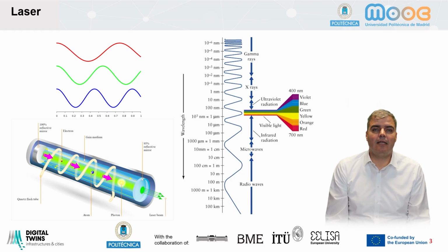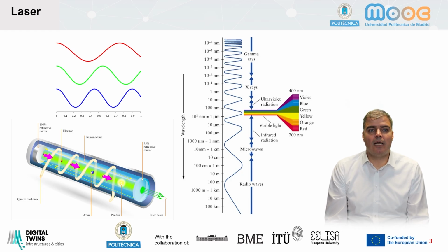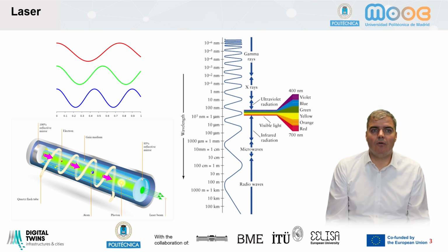The near infrared range that laser scanners use is around 1 micrometer, 1.5 micrometers, 1,500 nanometers. So there are different colors of lasers, but since they are very close to the visible range, it can be considered that if you can see through, for example, rain or fog or very light cloud, the laser can go through. Otherwise, it can't.